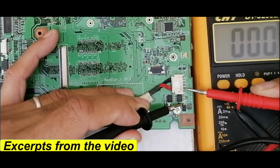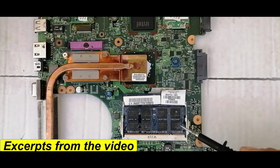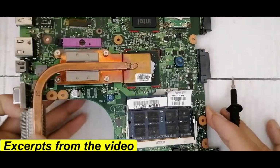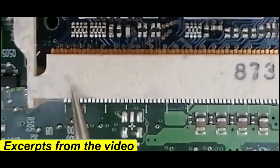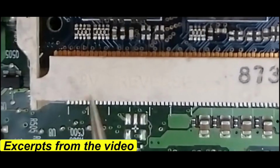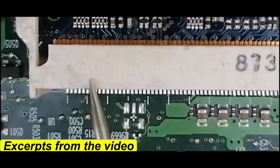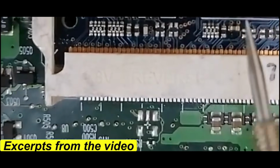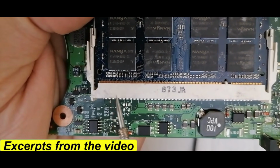How can we identify the type of this RAM? Easy. We can just look here at the slot. Do you see the voltage here? We have 1.8 volts. That means this is DDR2, because the voltage for DDR2 is 1.8 volts.